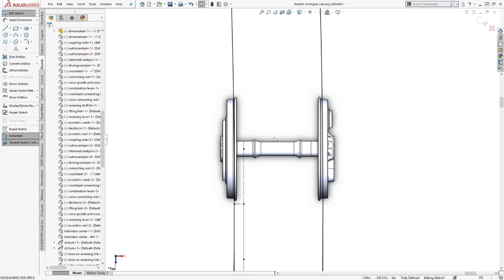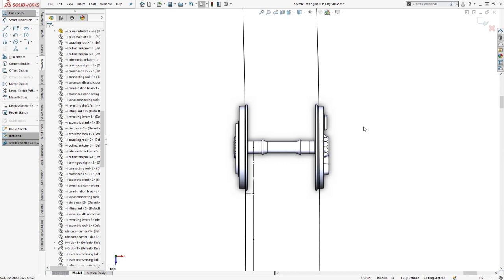For one thing, power's not coming in via a drive shaft running this axle. It's coming in by two steam cylinders. So to change the velocities of one side versus the other, we'd have to differentiate the steam flow. And it would be different for every single curve. It just isn't feasible. You need it to be automatic.